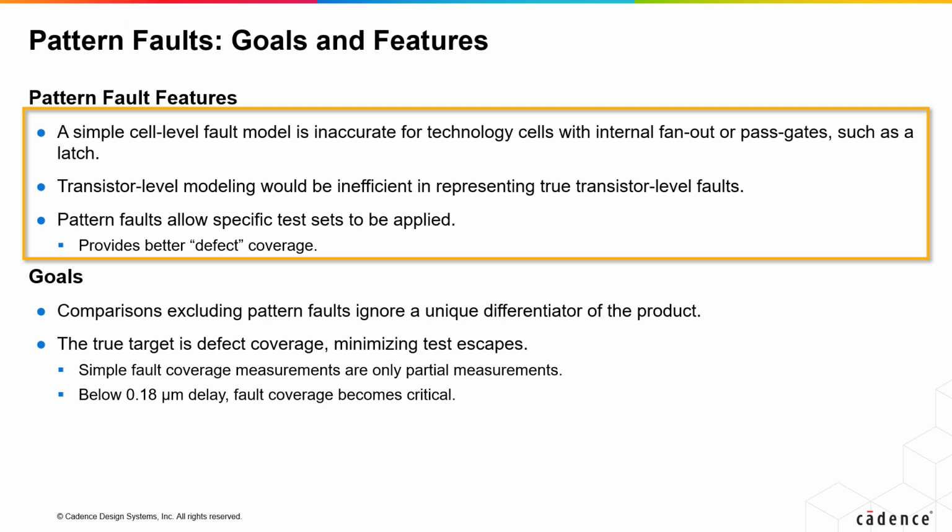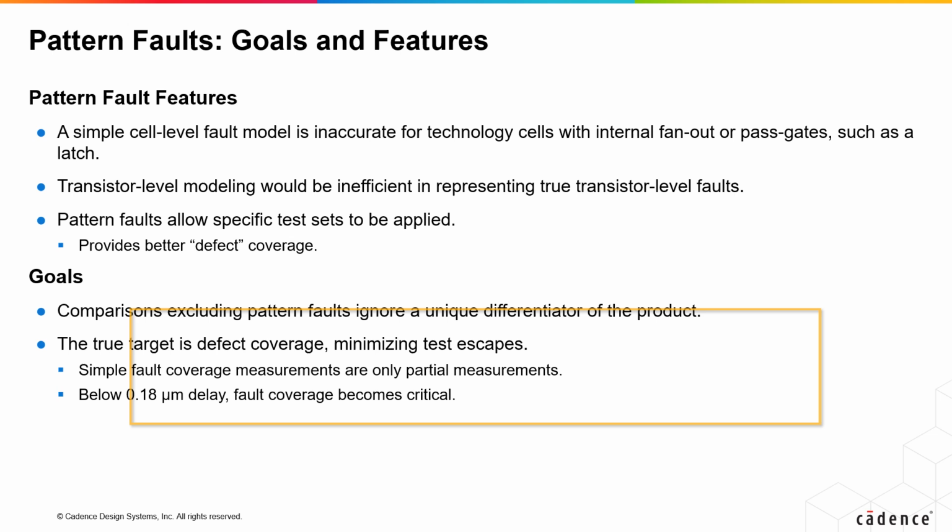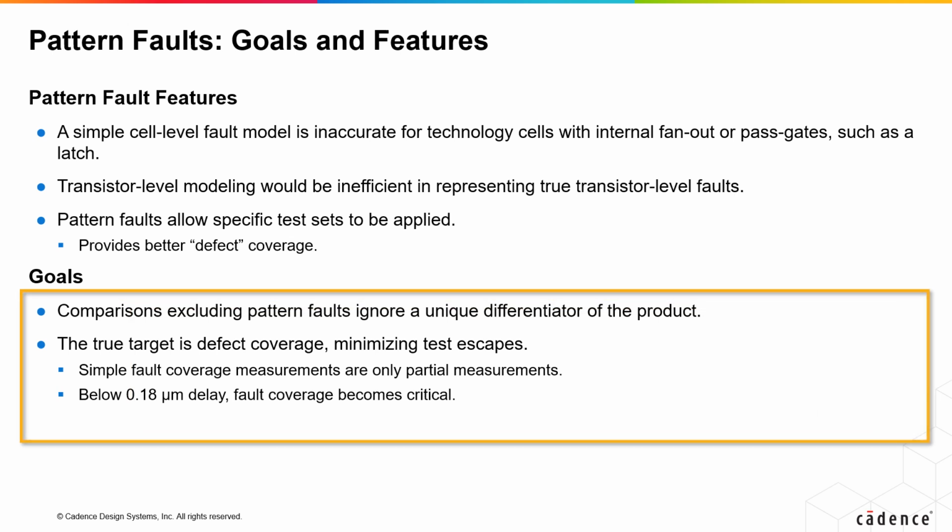Pattern faults allow specific test sets to be applied. They provide better defect coverage. Comparisons excluding pattern faults are ignoring a unique differentiator of the product. The true target is to increase defect coverage and minimize test escapes.